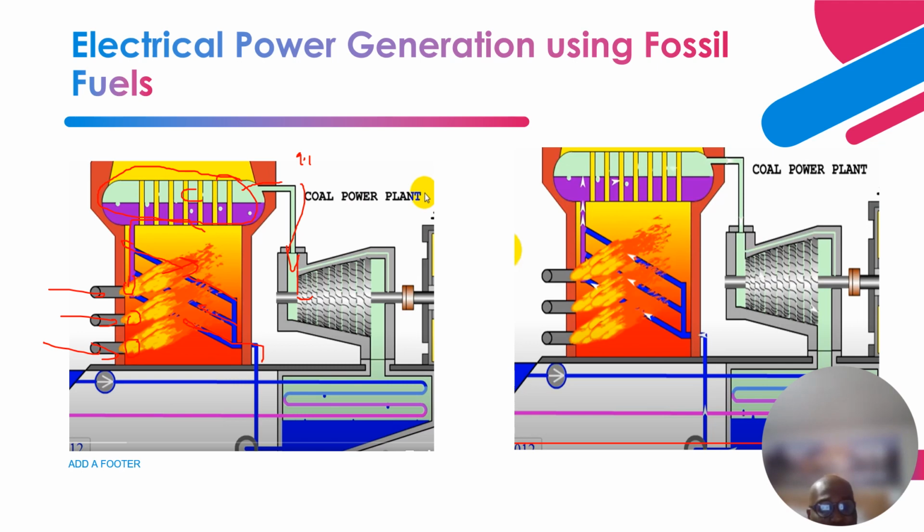As it goes through the turbine, it comes back here. This is a closed loop of cooling water that comes from the river on this side. As the steam from the turbine drops down and comes into contact with this cool water, it collapses into water.